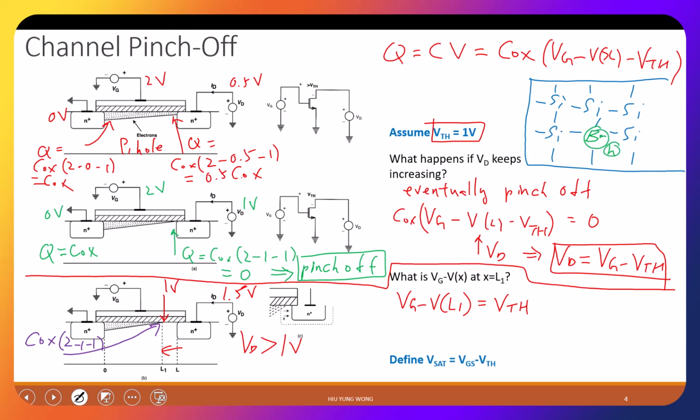The hole is the carrier in the p-type because you have 3 electrons, but then you just assume that I borrow 1 electron, then you have 4 electrons, you can complete this bonding. But then you create a hole somewhere, and this is the hole that is moving. We don't go to solid state physics, just think in this way.